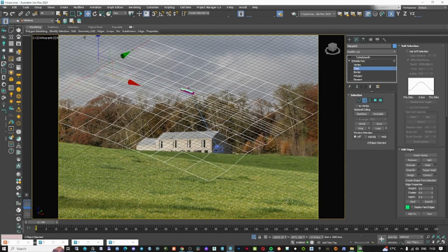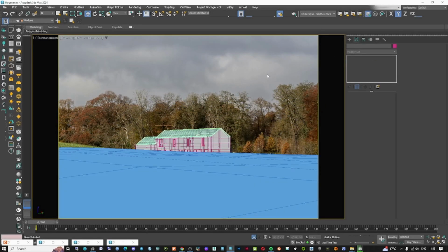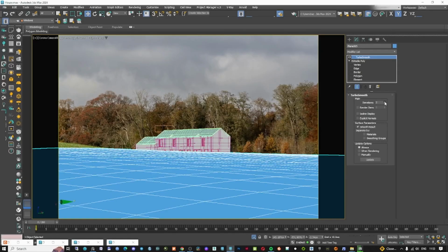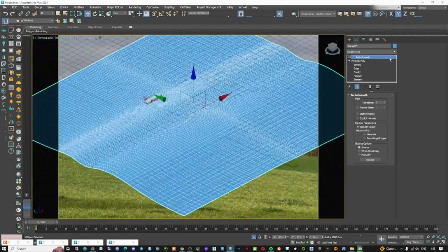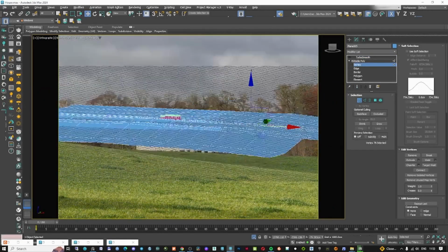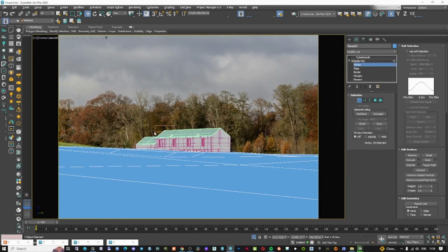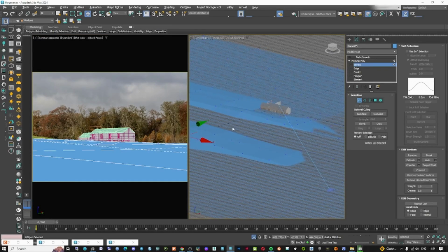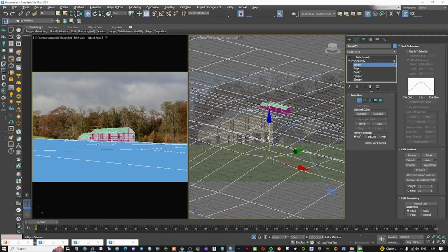When you extrude the edges in 3D Studio Max, it's good to always have the same distance between them. If it's possible, I know sometimes it's not working like that and it's quite hard, just try to keep the distance between the edges the same. In this way, later it's going to be easier to apply an unwrap or a UV map.